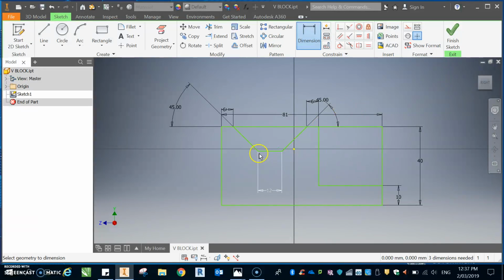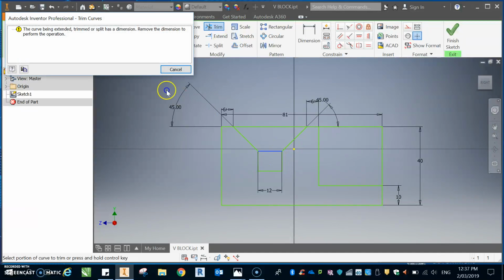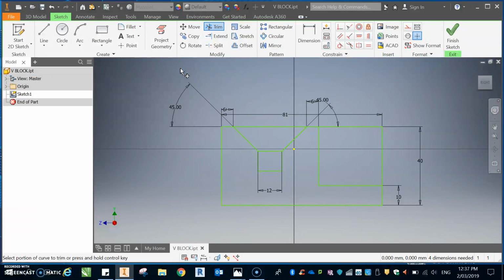Alright, so you can see that if you're having a look at the drawing, it's actually got a recess down here. I'm going to put that in right now. Here it comes. It should be automatically 12 mil. Across and up we go. Escape. Alright, so I'm going to trim this. Just trim that. This comes up here, so what I'm going to do is get rid of that dimension up there, escape, which isn't a problem.